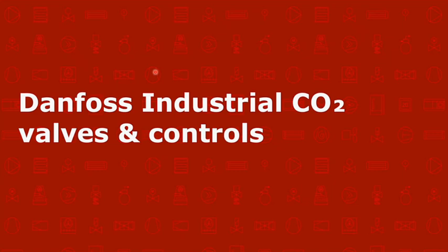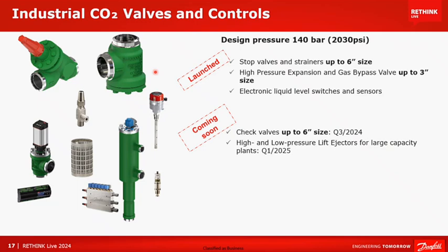I already mentioned that we are growing large in our compressors. This is not the only component, though, that we are growing larger. We started a couple of years ago the launch of our CO2 transcritical industrial valves, where available in Cool Selector are already multiple valves rated up to 2000 psi pressure. We also have larger control valves, among others, up to 3 inches, which can be used for a high pressure gas bypass valve. But what is really interesting, which is improving energy, is the ejectors.